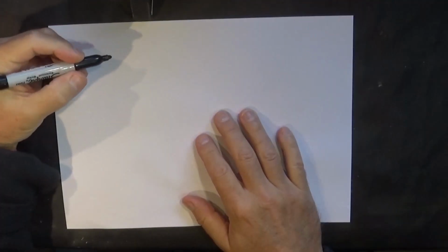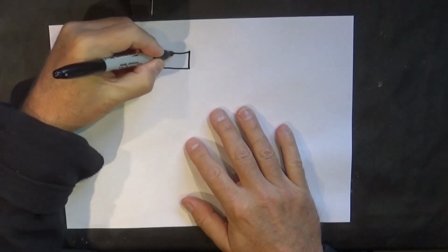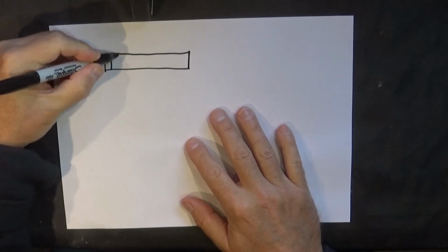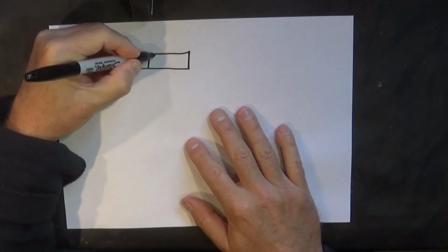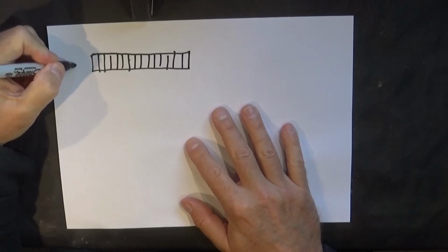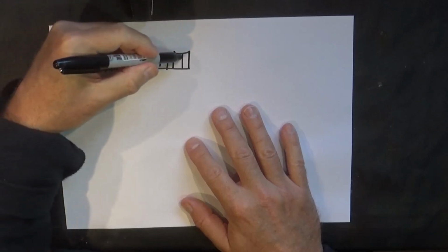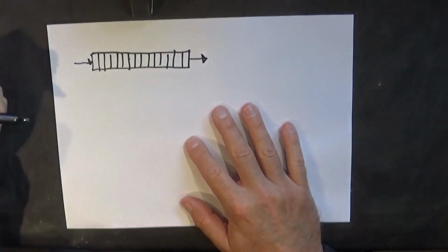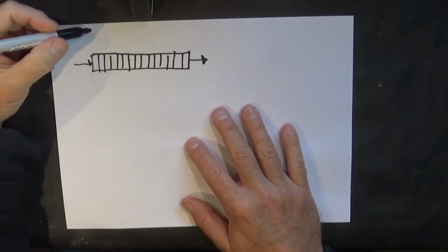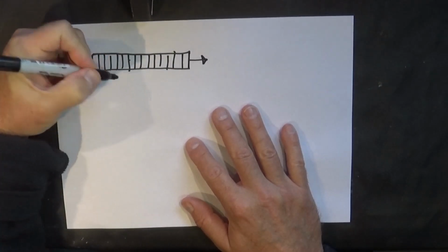Okay, a delay line. It's very simple in concept. You just have a lot of memory locations like this, and every sample you put a value in at that end, shuffle all the others down and take one out at that end. So there is a delay time of N over the sample rate.